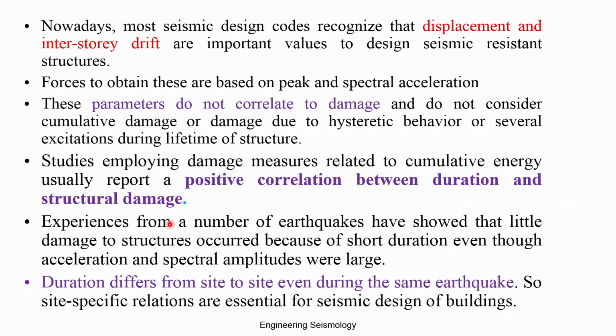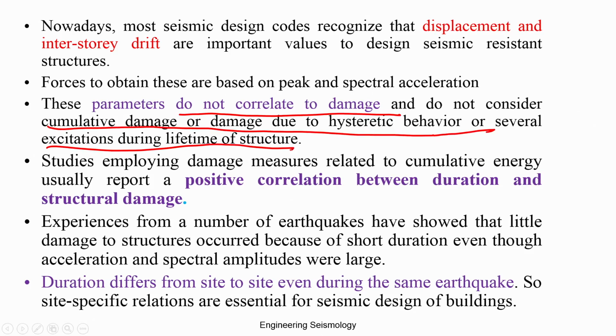Nowadays most seismic design codes recognize displacement and inter-story drift as important values for designing seismic resistant structures. The forces obtained are based on peak and spectral acceleration. These parameters do not correlate with the damage, and do not consider cumulative damage or damage due to the hysteretic behavior of the several excitations during the life of the structures.